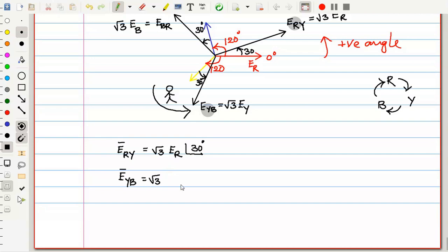How we get it is in this way. Just let me put it here for your understanding how we got that minus 90: EY phasor into 1 at an angle of 30 degrees basically. For this phase voltage, it is multiplied by 1 at an angle of 30 degrees. That means this line voltage is leading this phase voltage by 30 degrees. That is the importance of this term.